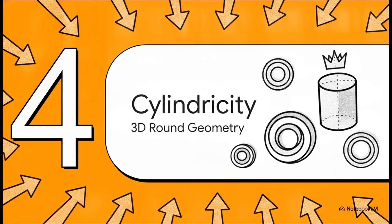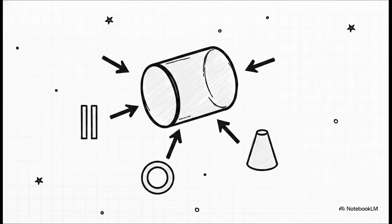Number 4. Cylindricity, 3D round geometry. To catch that barreled or wasted defect, we have to move to the bottom right of our matrix and unleash the absolute boss-level 3D symbol for round geometry. Cylindricity is the one symbol that practically everyone underestimates, but manufacturers respect it deeply because it's a strict, all-encompassing control. As the ASME standard explicitly points out, cylindricity is a massive composite control of form that commands three things all at once: the straightness of the cylinder, the circularity of the cylinder, and the taper of the cylinder. It evaluates the entire feature at the exact same time.